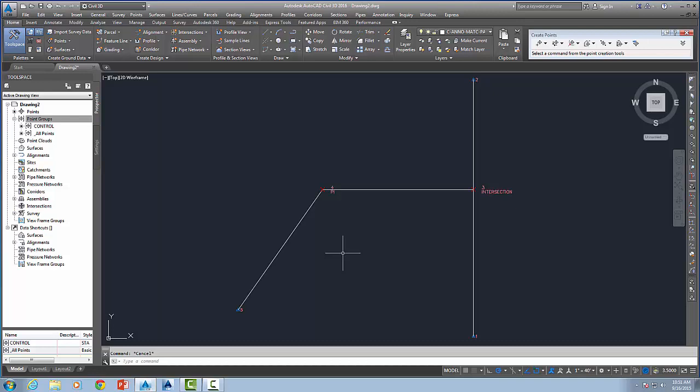We're going to establish it, and we have several different ways. You could use the AutoCAD fillet command, but if you did, it would force you to calculate the radius yourself. And then of course you have rounding issues, because if you notice you've got 30 degrees, so you know that your radius is going to be at a 4 or 5 or 6 decimal place value if you really want to get it exact.